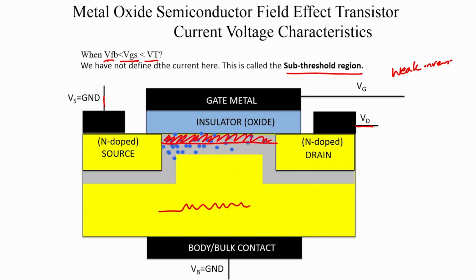It was like one long resistor connecting source to the drain, and therefore the drain to source voltage was spread across this resistor. So, as you moved from the drain to source, every electron felt the field of VDS, and therefore we could model the current as a drift current.